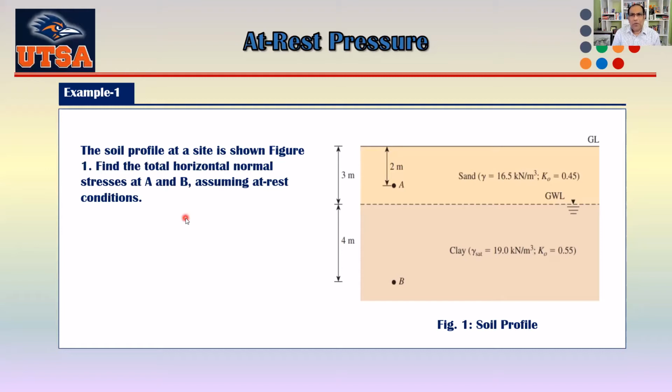One thing I must say here is that from the theory, you can only find the lateral pressure from the soil. But if you have a water table there, you can understand that there would be pressure from the water to the wall too. From the theory, you can understand that water pressure is equal in every direction. Now let's move forward to our board and try to solve that one there.